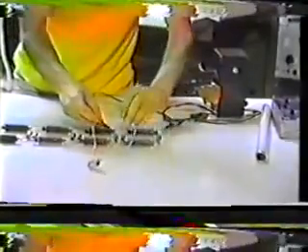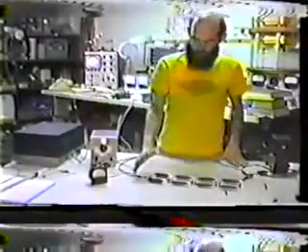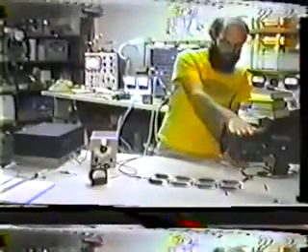Now with the dielectricity we can start from the end, bring the bulb out of overload a little bit. And we can probe down to the next stage. It's a little weaker. And here it's not even measurable anymore. So the dielectricity has dropped off going this way and the magnetism has gone this way. So we can see our classical distribution of magnetism and dielectricity on a TEM line, where the magnetism rises towards the low impedance source and the dielectricity rises towards the open circuit or high impedance load end of the line. Of course, no load being hooked up at this point.